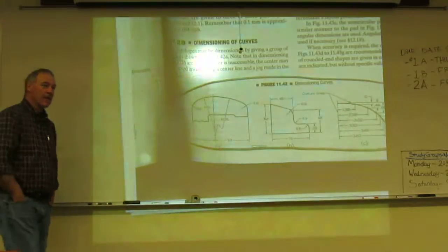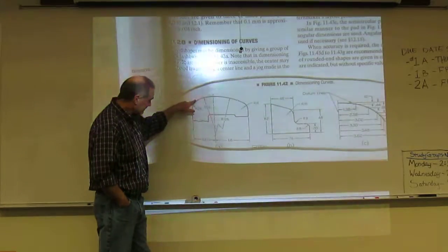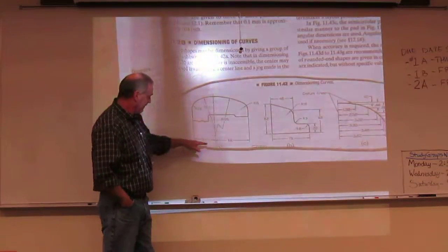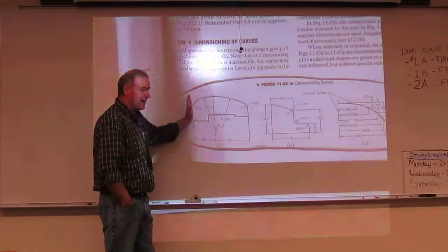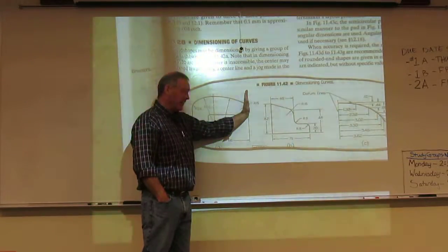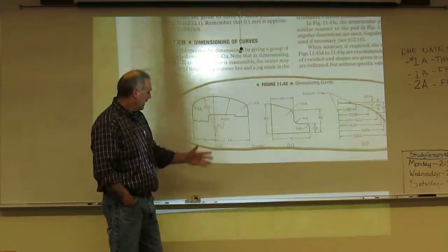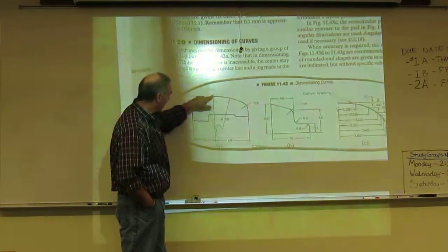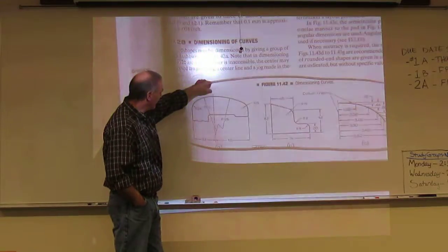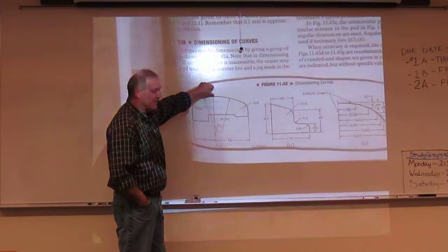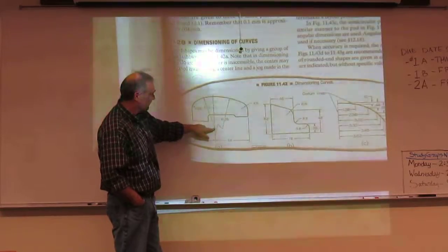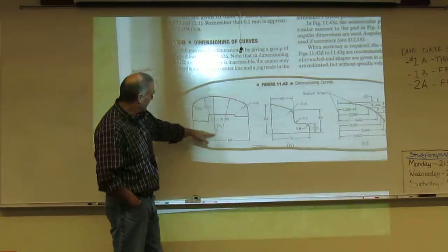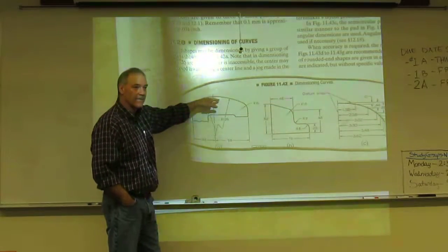No, not really. I mean, this right here, and how we get that? Well, if you were to draw this, what would you need? You would need that line, and then you would offset that to get that edge. You would offset that to get that edge. Now, other than that, you don't need anything else, because you're just going to pick a spot, and that's going to drive that guy, right? Okay. So we would start right here, probably. Draw a circle back, that's going to give us that center. Then we can build this arc and we can build that arc. Well, we got one more in here, that's this one.